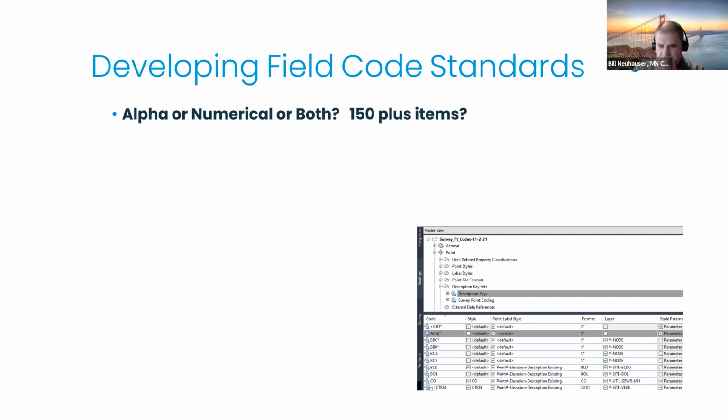On the numerical list, one thing I like to do though is I like to have the numerical with some alpha at the end, and my alpha is designated for my line work, which we'll talk about in a little bit here. And so it's an easy way to separate between what was intended as just a shot or what was intended to be line work. Again, trying to make this simple so that error corrections pop up, slap you in the face so it's easy to find.